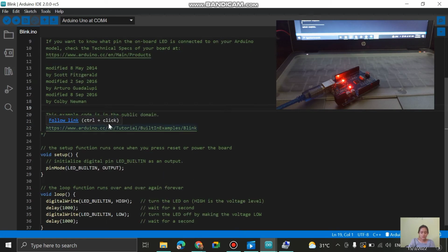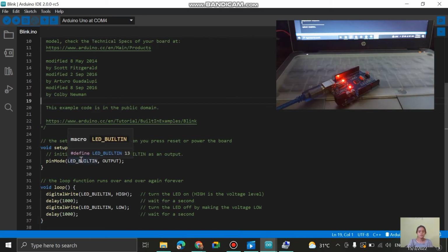We may need to discuss some of the functions here first. The information given says the setup function runs once when you press reset or power the board, and we already powered up the board. In order to run a sample Blink program, we need to set the delay to 250 milliseconds for the on and 100 milliseconds for the off, or low.